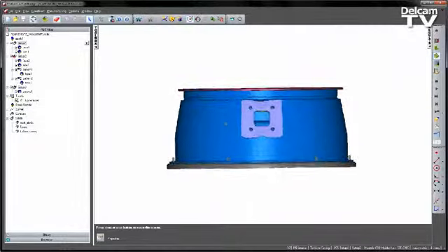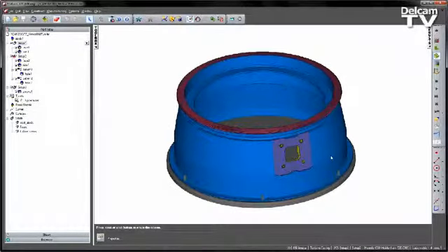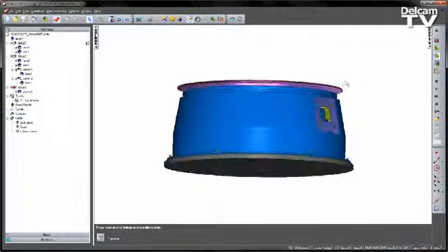You can now see the milling features that I've created. I can then finally switch to setup 3 and again resimulate, and this will simulate the grooving operation under the component to complete the features that I've created in this particular example.